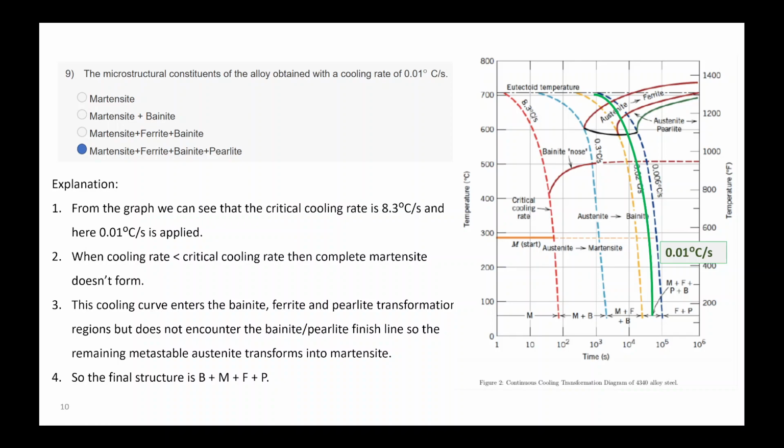No, but compared to iron carbide, cementite, martensite is highly metastable. If you heat it up to 50 degrees Celsius or something, it might convert into other phases, for example, when you provide heat treatment, tempering. In that case, you heat your steel up to 200 degrees Celsius or something like that, then it can change your martensite to bainite or other phases.